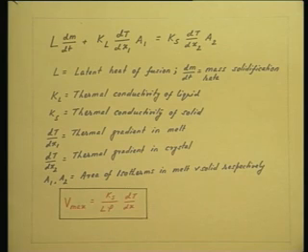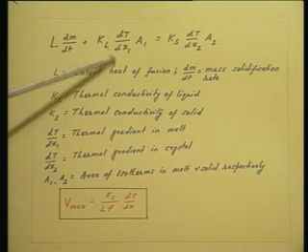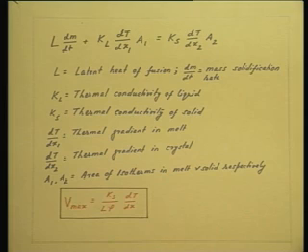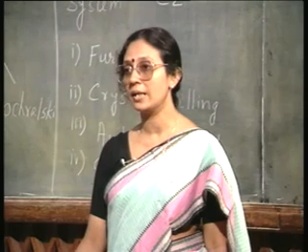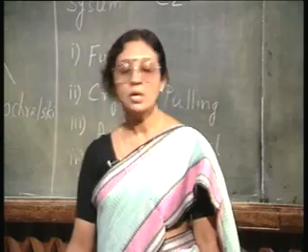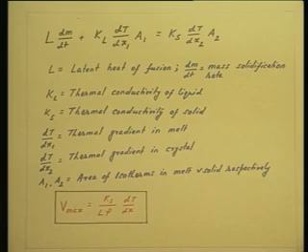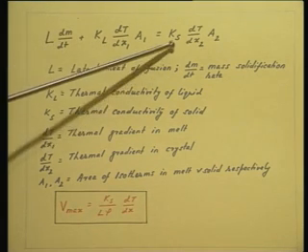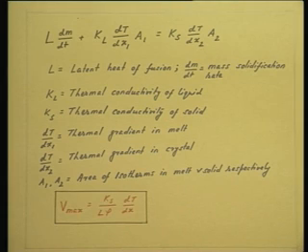Now, from this equation you can very easily see that if I assume that the thermal gradient in the melt is 0, that is the entire melt is at a constant temperature, that is, it is maintained at the melting point. So, if dT/dx1 can be made equal to 0, then L dm/dt is going to be equal to K_s dT/dx2 times A.